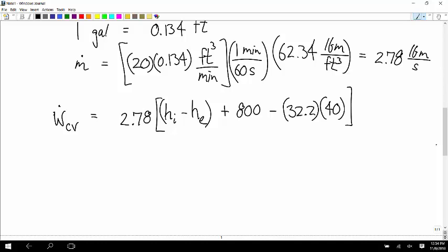And so we're going to say this and this. Since the pressure and temperature are enough to specify all the other properties, that means that there's not going to be any change in enthalpy at the beginning or the end. So HI minus HE is equal to 0. Everybody with me on that?